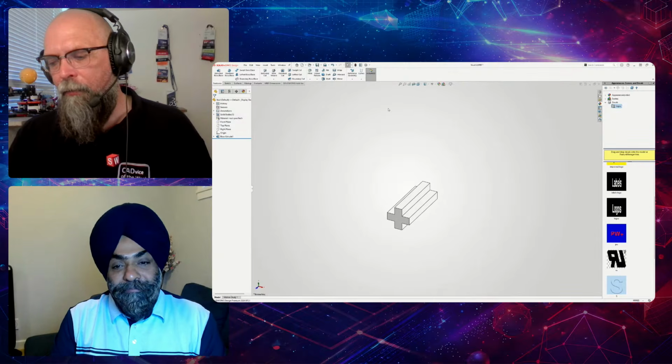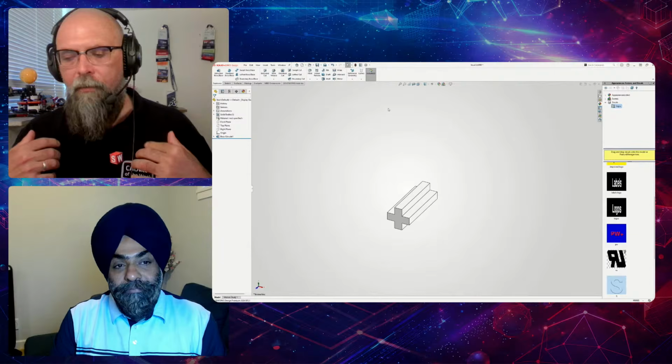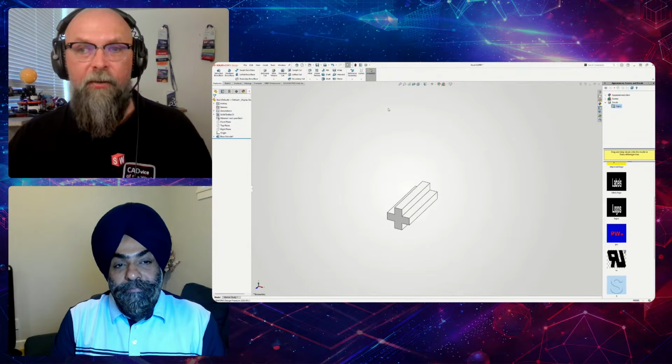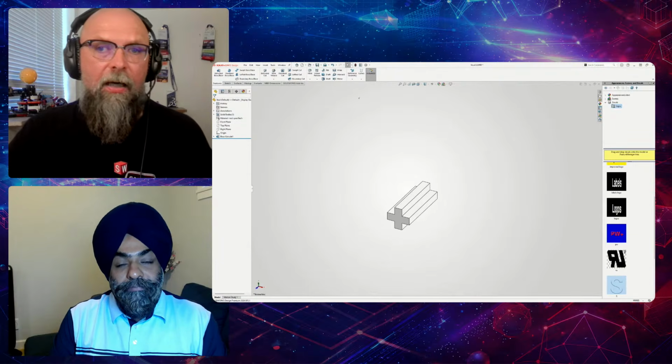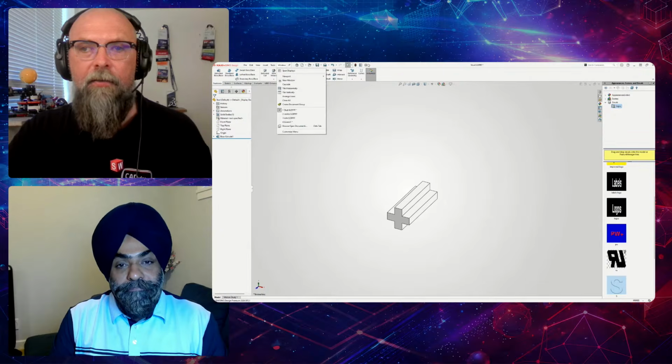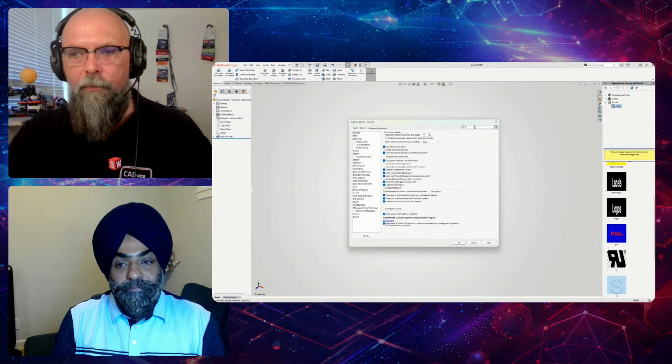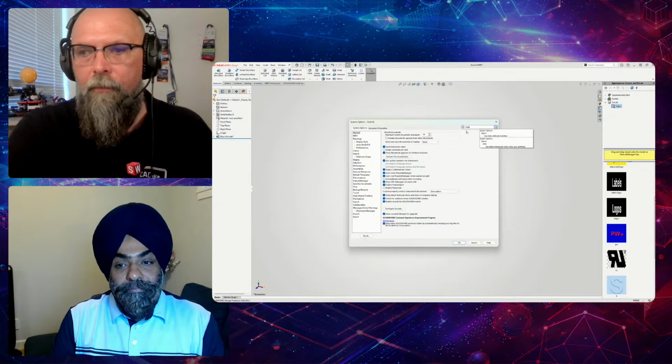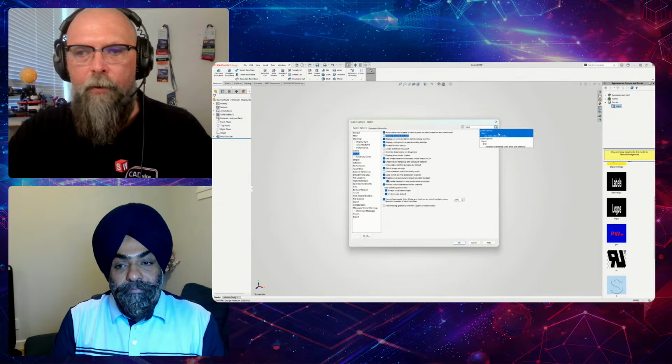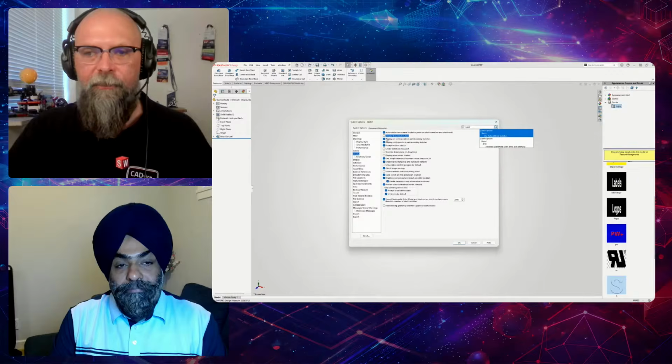Yeah. I would also say one more thing. If you often find yourself thinking, okay, I usually forget to fully define my sketch, then SolidWorks has another tool for you. Just type in, so we have this one here, use fully defined sketches.